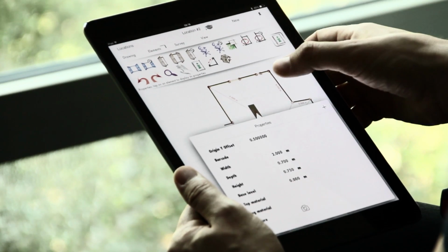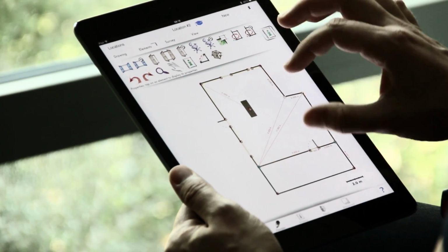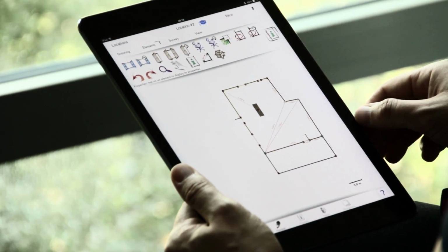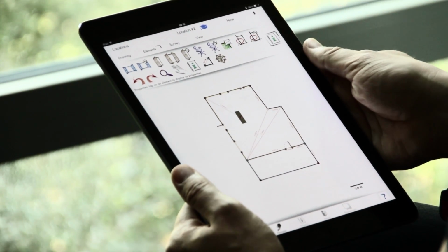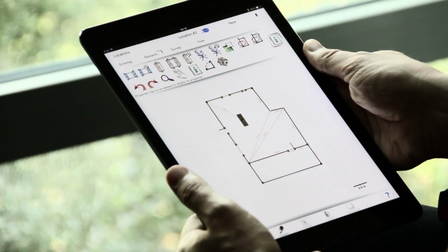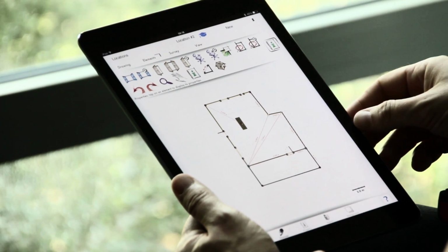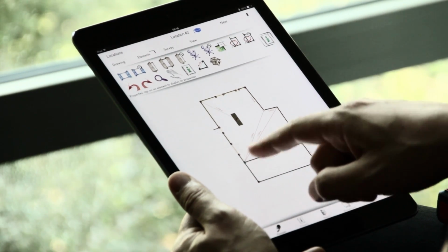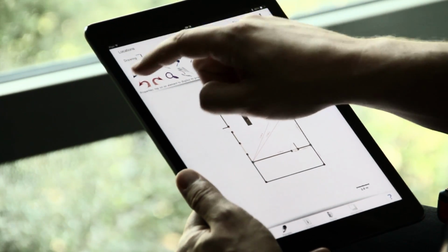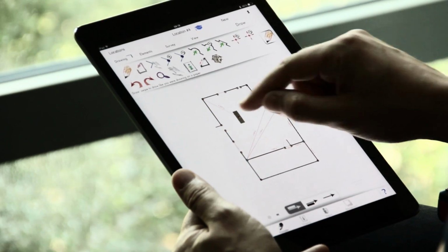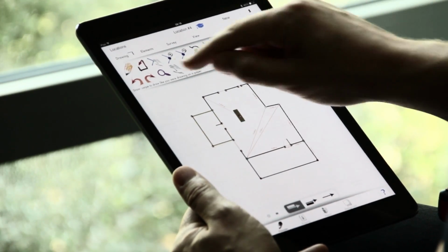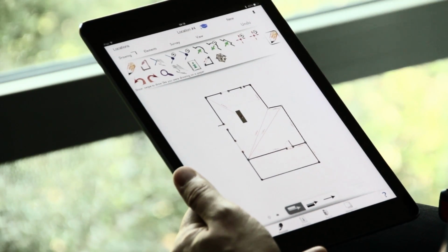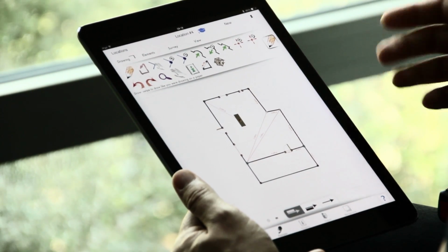The next step we are going to take is to talk a little bit about how to sketch new rooms, because there are many ways to do sketching in OrthoGraph. One I already showed you before. You can sketch a room and tap on it and it attaches automatically. Let me just refresh your memory with this one. That's what I did before, but I'm going to repeat it. So I just click on the pencil, sketch the room, and if I tap on it, it's going to be attached automatically. But let's just go one step back, delete that room, and assume that you want to sketch differently.